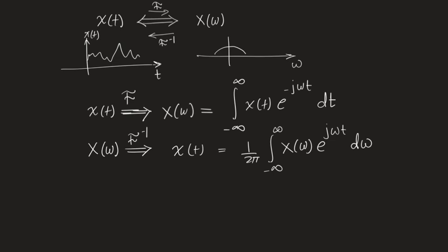So these two processes look very similar, right? The signal multiplied by e to the j something and integrated, the signal multiplied and integrated, the integration from minus infinity to infinity. The difference is only a plus and a minus sign here, and just a scaling factor here. So the two operations are very similar to each other. And we'll see that this similarity is helpful to solve some issues as we come to this later.